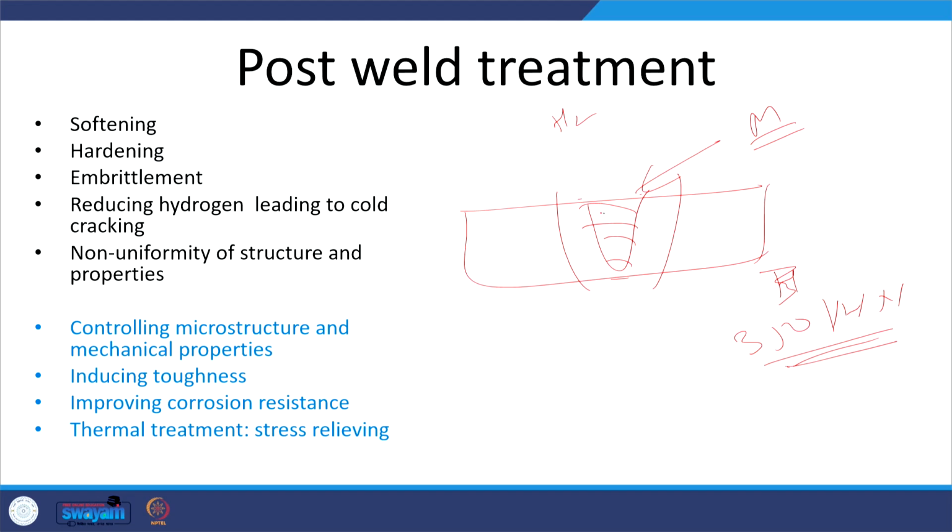Then this hydrogen gets diffused into the heat affected zone, and there it promotes cold cracking, or delayed cracking.